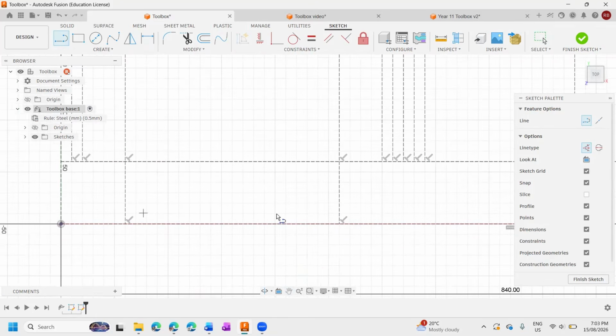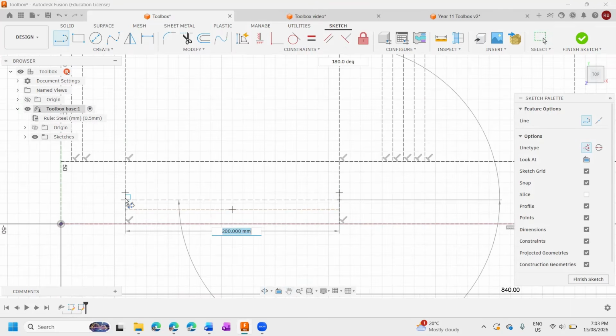Then we want to make another 2 more tabs across. Any sort of size, just as long as it goes across. Now, what did come up there, which a lot of you might have an issue with, is see that blue triangle? We don't want to be clicking where it turns up with that blue triangle because for some reason it does a funny constraint error and it's really annoying. So just try to move and start somewhere else.